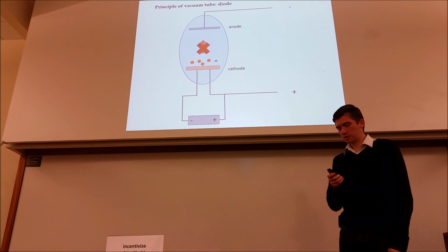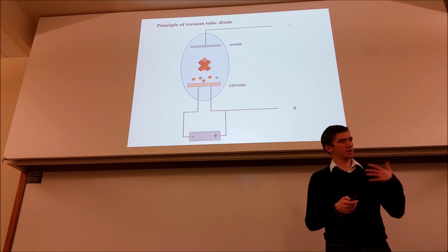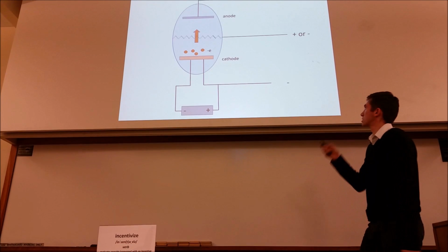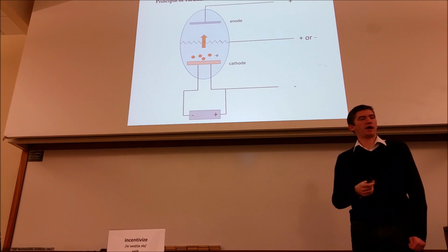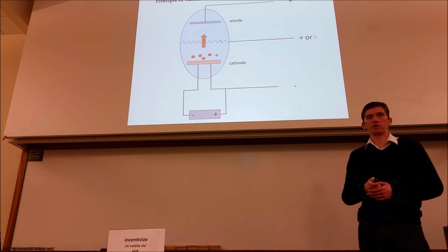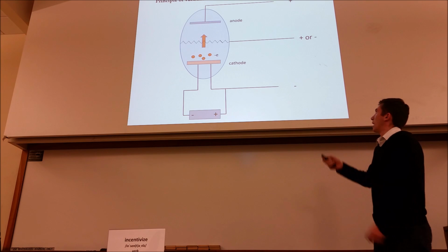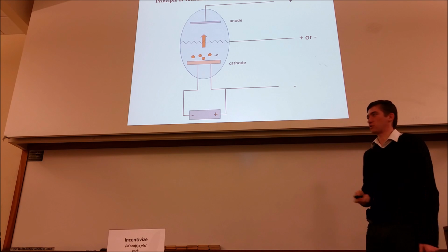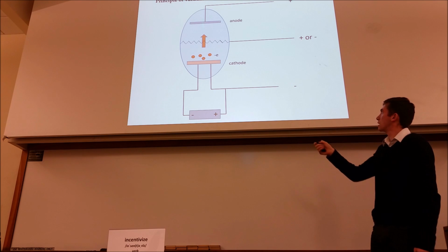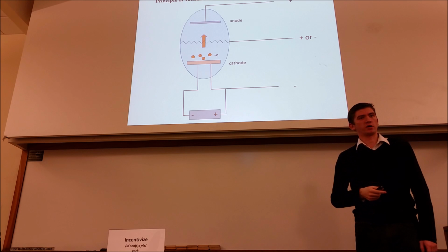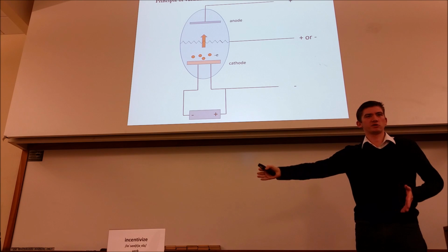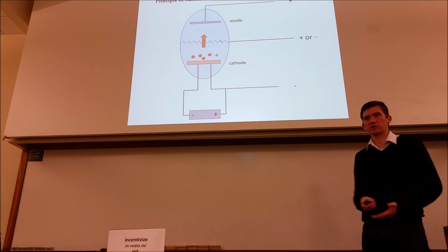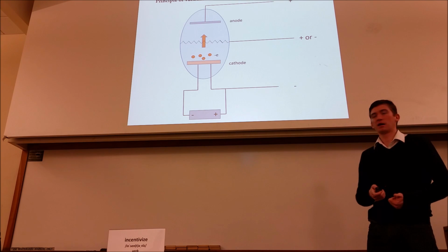And what people noticed is that this was working well, but not good enough. So they introduced one more thing, an electrode in between the cathode and anode. And now we have what is called a triode, since there are 3 electrodes. This electrode works as a door, which either lets the electrons walk in from cathode to anode or locks the door and does not let them pass this area.